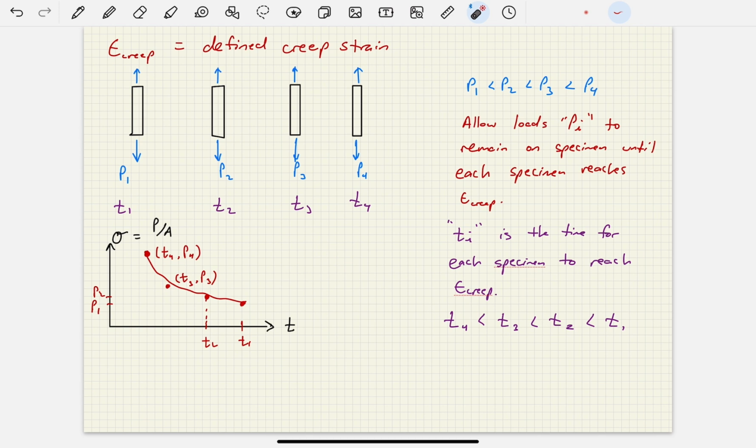Okay, now why is this important? Again, in engineering and all forms of engineering, especially applications in civil and mechanical and even biomedical, maybe aerospace engineering, you're going to have components of things that you're designing that have to sustain a load for a long period of time. And you might need to do a creep analysis. Now, not every situation of design will need a creep analysis, but some will, especially small components that maybe have very small cross sections, or components made of materials that are maybe not very strong for some reason. Maybe you have a polymer material that is supporting a large load for a long period of time.